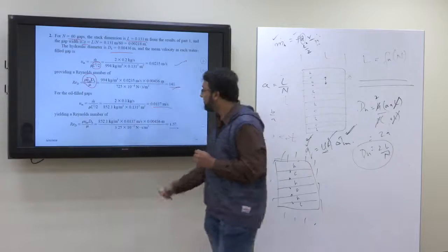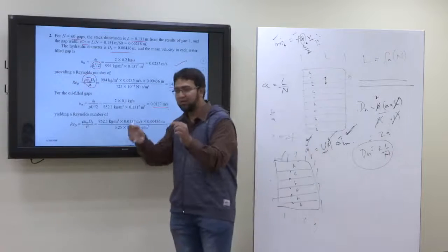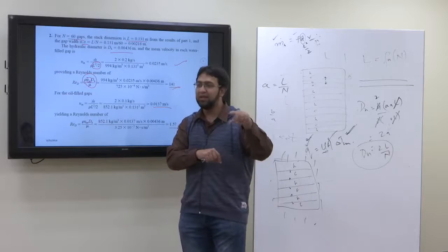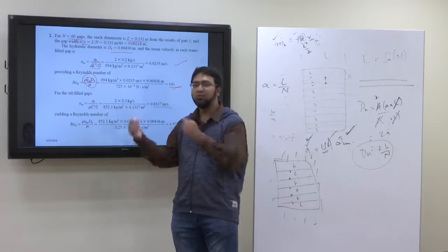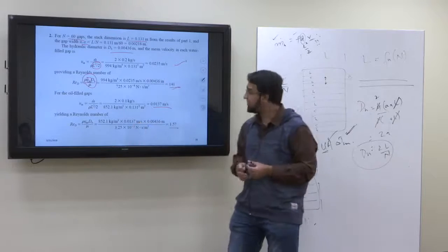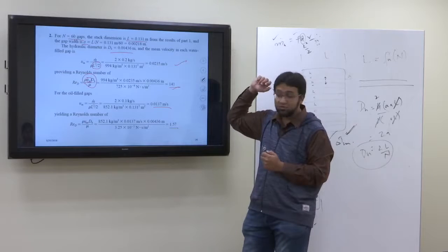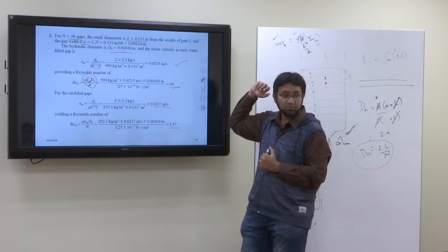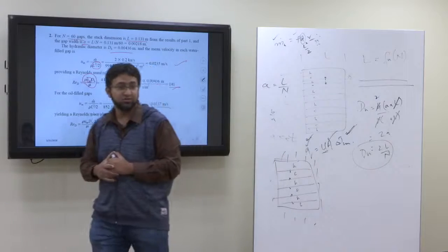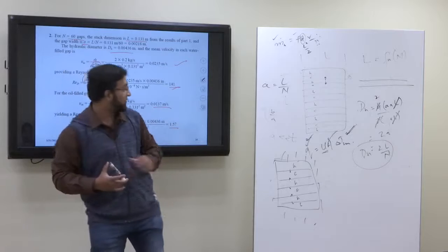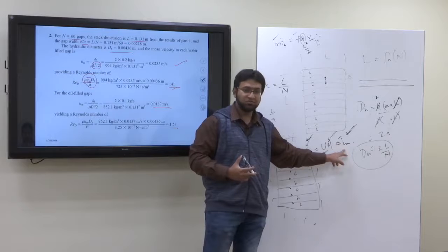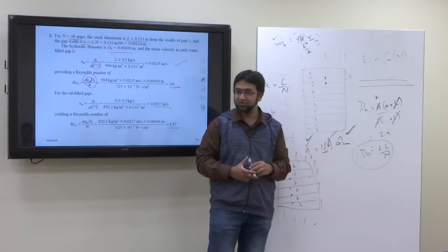Actually, the thing is that it will be laminar flow, but previously we did not need Reynolds number in any formulation. Now we need Reynolds number in the formulation. At which temperature do we take the viscosity? At the average of inlet and outlet. We already know the average of inlet and outlet because by the time we were finding Q and delta T LM, we determined the inlet and outlet and the average.